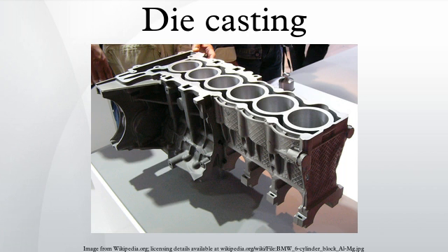The cover die is secured to the stationary, or front, plate of the casting machine, while the ejector die is attached to the movable plate. The mold cavity is cut into two cavity inserts, which are separate pieces that can be replaced relatively easily and bolt into the die halves. The dies are designed so that the finished casting will slide off the cover half of the die and stay in the ejector half as the dies are opened. This assures that the casting will be ejected every cycle because the ejector half contains the ejector pins to push the casting out of the die half.